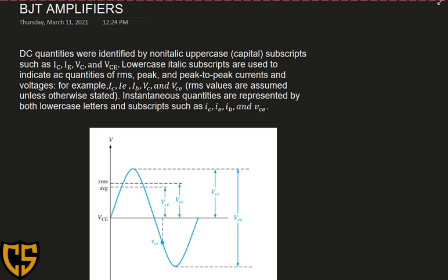The biasing of a transistor that we learned is purely concerned with DC operation. The purpose of biasing is to establish our Q point, or quiescent point, about which variations in current and voltage can occur in response to an AC input. In applications where we consider small signal voltages, the signal we need to amplify is small, such as, for example, from an antenna or a microphone. So variations from the Q point are relatively small.